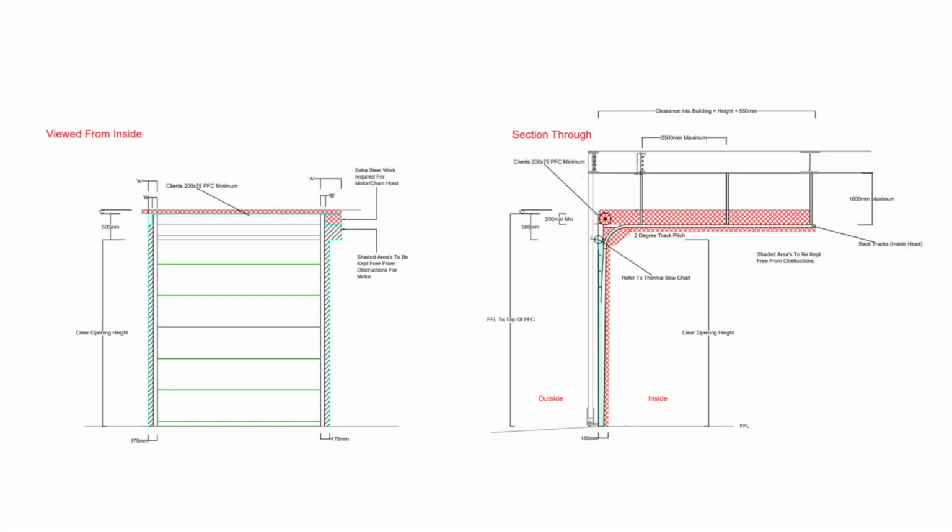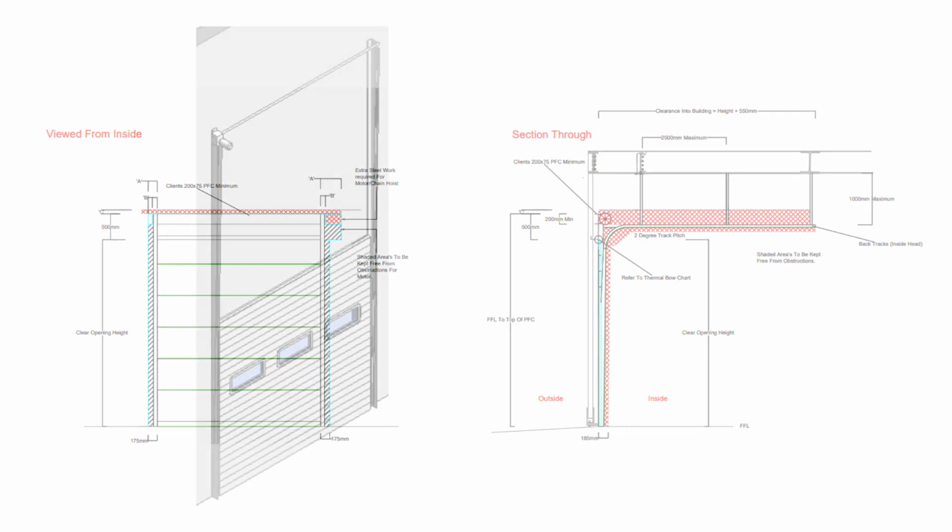For manual doors, push-up and chain operated, the counterbalance and cable system allows for quiet and straightforward operation. Electrical operation is available, offering a variety of operator options to accommodate the specific needs of clients. The door sections are crafted from double-skin steel sections filled with PU foam made from hot galvanized steel with a depth of 40mm and finger trap protection. Alternatively, there is an 80mm depth option for increased performance or larger sizes. These panels are available in 2 textures, stucco and micrograin, and can be finished in various RAL colours.